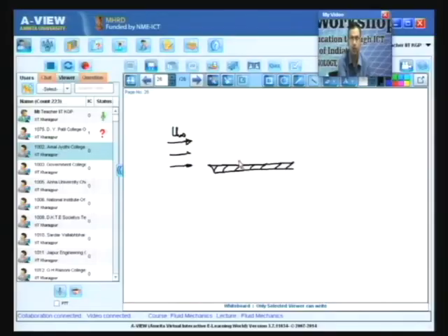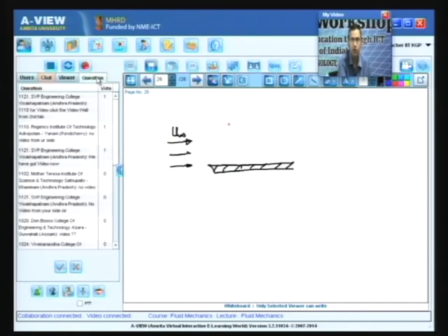discussions. The next concept that we will discuss is viscosity. The first layer of molecules which is interacting with the plate attains the velocity of the plate. This is the so-called no slip boundary condition. There are exceptions when this boundary condition may not be valid, but here we discuss situations in this particular introductory course where we assume that the no slip boundary condition is valid.